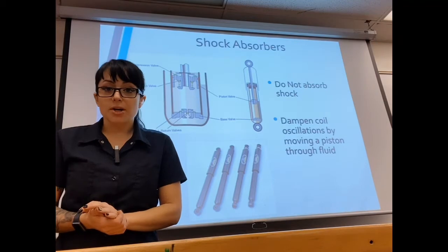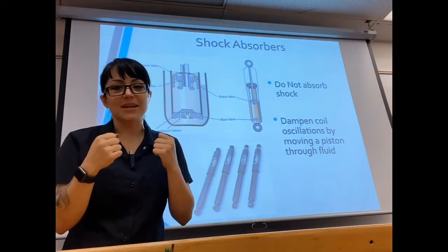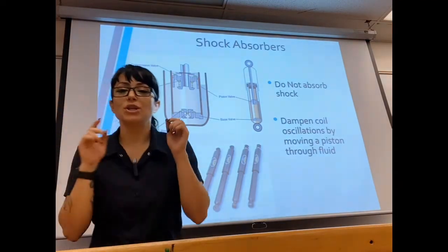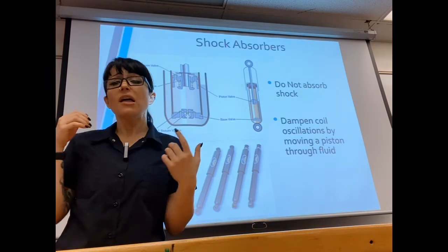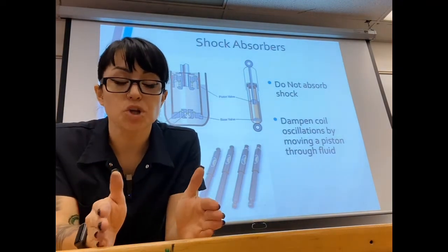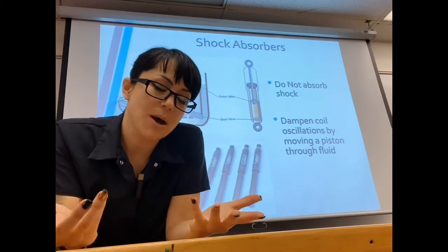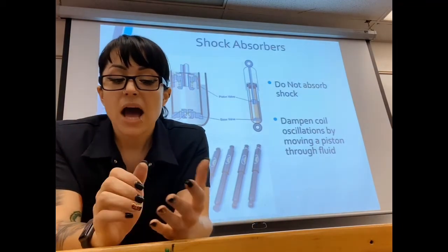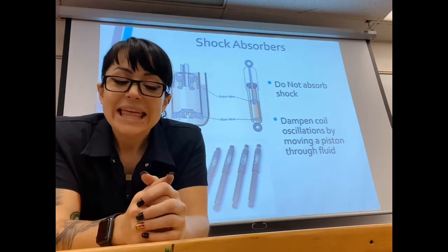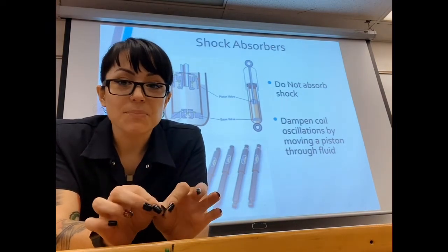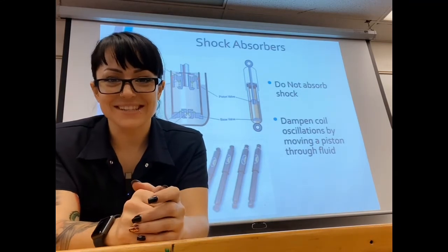Shock absorbers, and I've been saying this term over and over again, and now I'm excited because we're finally here. Shock absorbers do not absorb shock. That's not their job. The job of the spring is to absorb shock, which is funny because we call them shock absorbers. I didn't make this name up, but it's an industry term. What do the shock absorbers actually do then if they don't absorb shock? They limit or dampen the amount of spring oscillations. Well, that sounds super fancy, doesn't it?